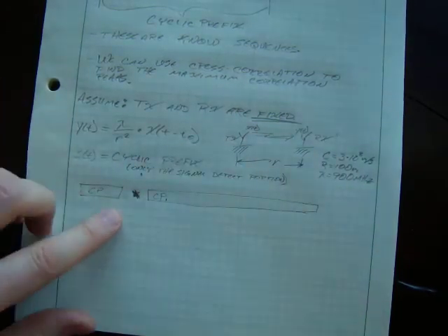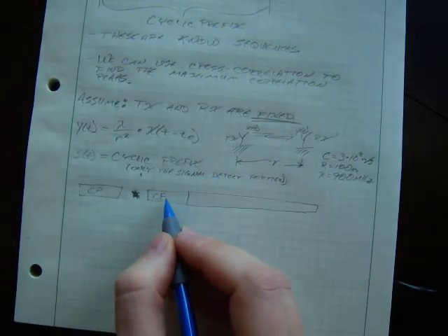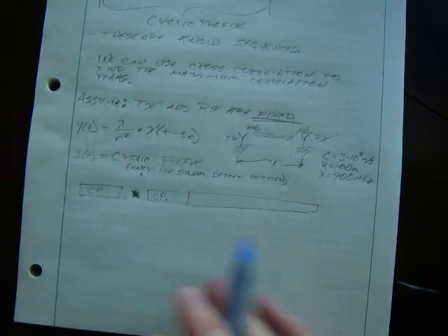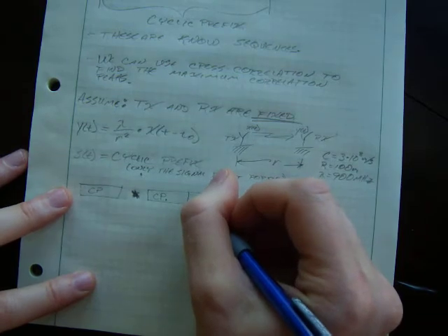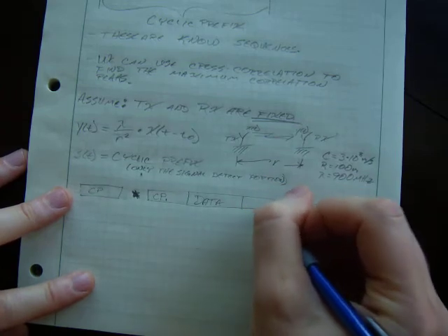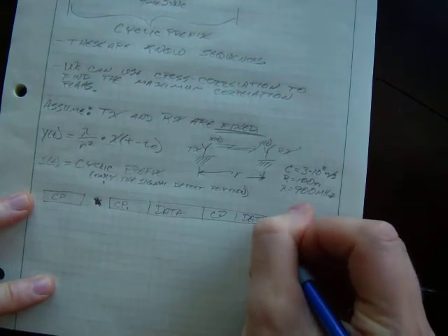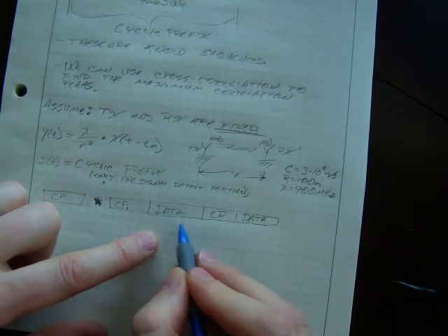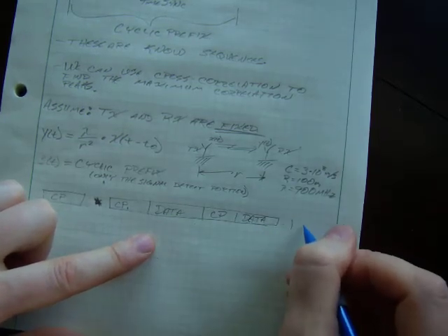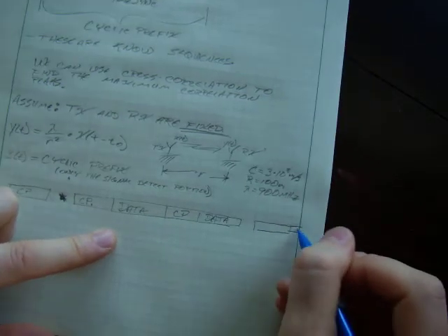So CP1, I'm just saying that there is some attenuation and there is some time delay. So there's some difference. And I'm just showing this so we can conceptually understand what we're trying to do. Then there's going to be some data portion of the message. And then after that is going to come another cyclic prefix. And then there's going to be more data. And these things are going to be spaced equally. And then there's going to be another cyclic prefix and then more data. Okay?